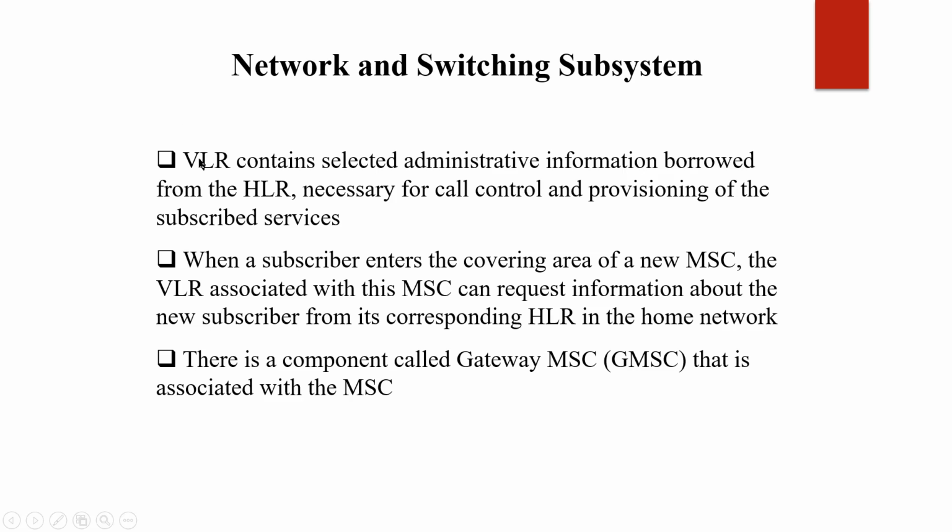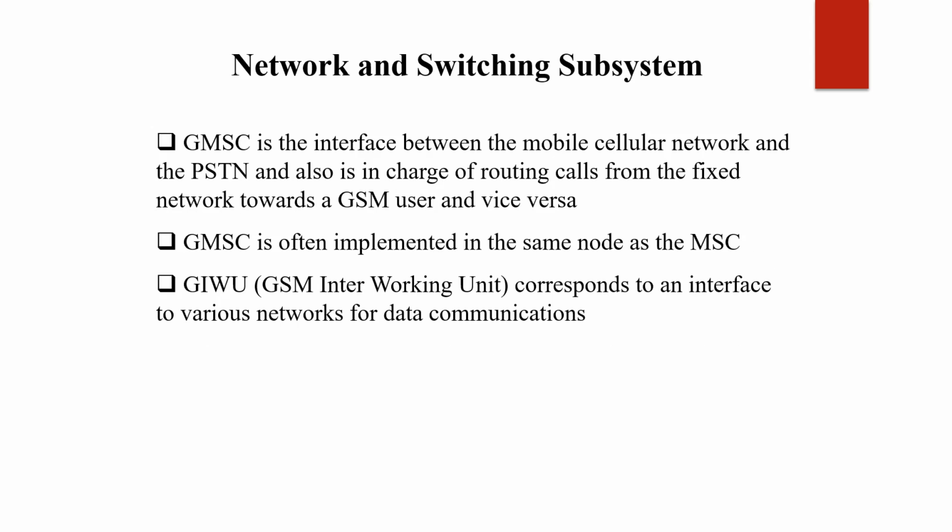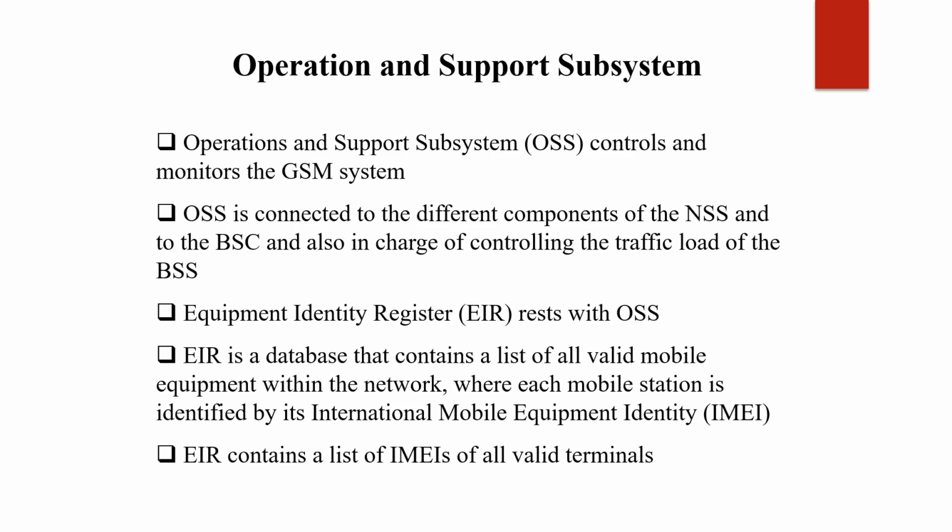The next component is the gateway MSC, that is GMSC, which is associated with the MSC and is responsible for connecting the cellular network and the PSTN, and is also in charge of routing calls from the fixed network towards the GSM user and vice versa. Okay, so this is all about your NSS subsystem.